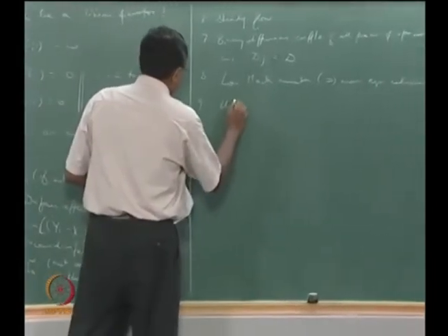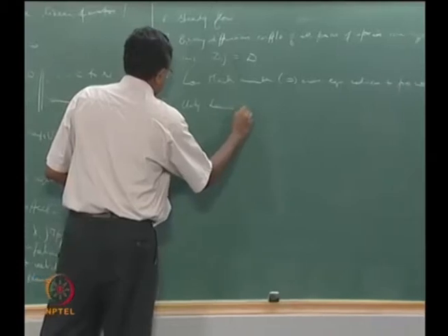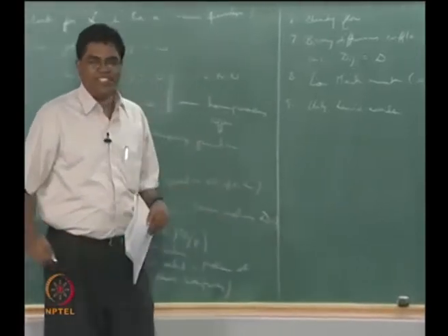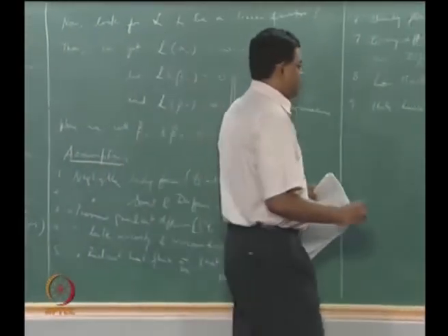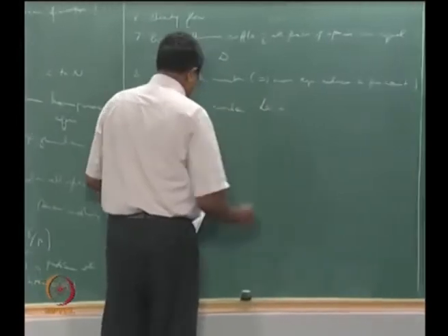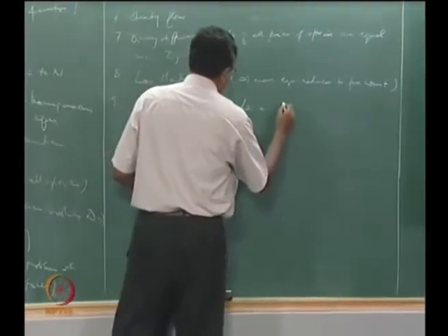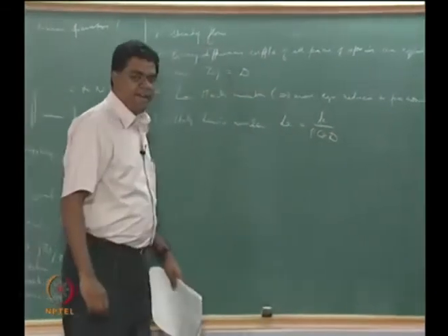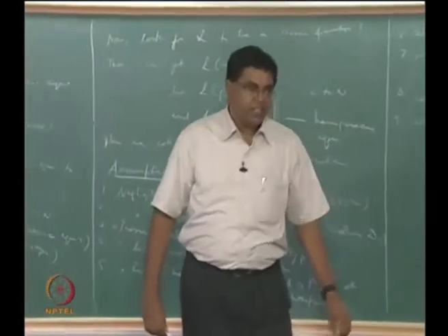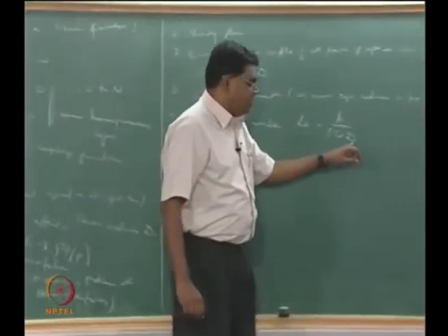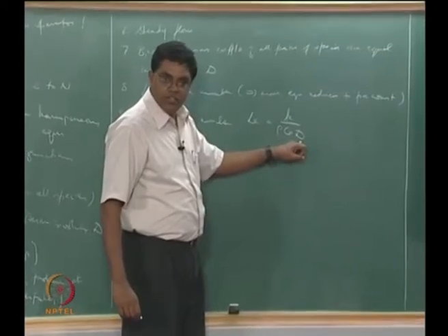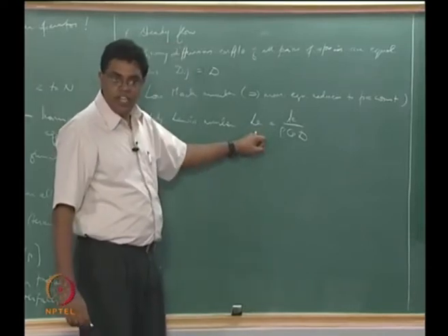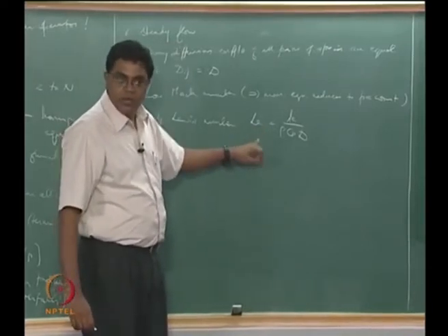Unity Lewis number. Right, so the question is, what is the Lewis number? The Lewis number Le is K divided by rho Cp D. Now keep in mind that D should really be like Dij in reality. So correspondingly you should have a Lewis number that is like Leij.